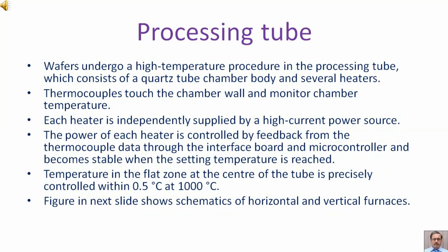Processing tube. Wafers undergo a high temperature procedure in the processing tube, which consists of a quartz tube, chamber body, and several heaters. Thermocouples touch the chamber wall and monitor chamber temperature.